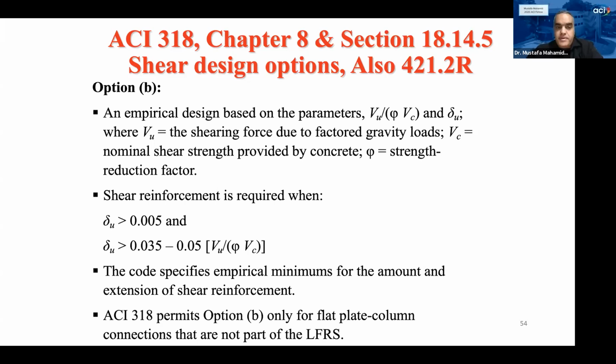This is very important. It's not like if the slab-column frame is not the lateral force resisting system, and we're providing shear walls or moment frames, punching shear will not happen. No, it may happen. That's why we have to check that. So here it says if we are using this, the slab should not be part of the lateral force resisting system, but we have to check it.